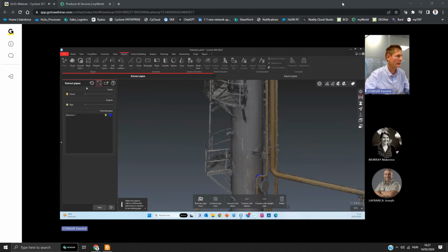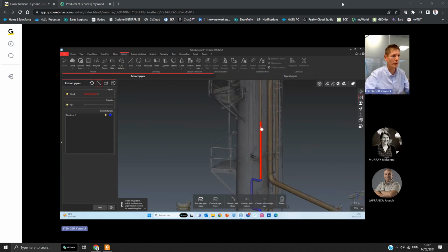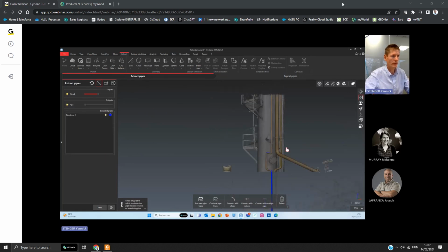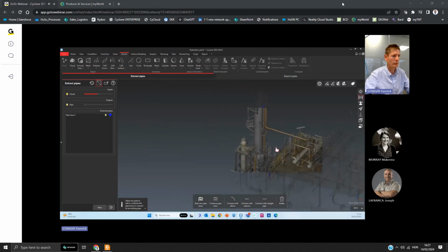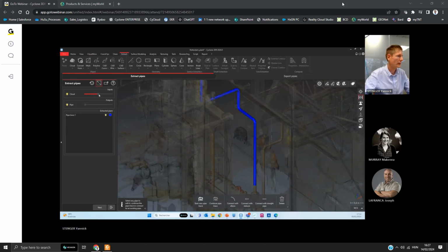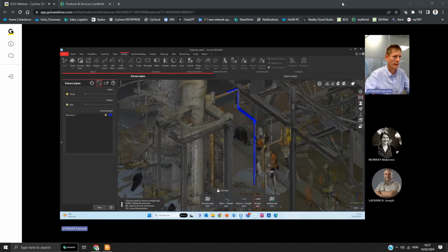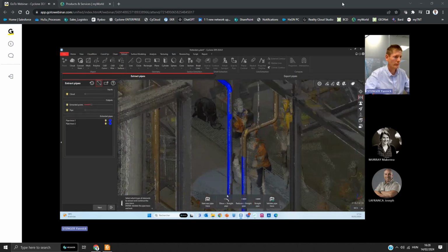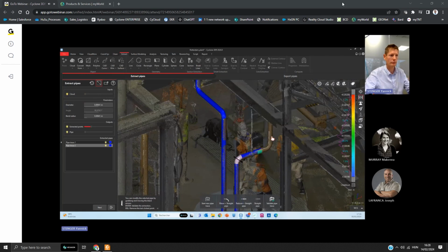And okay, if I'm satisfied. Also, nice tips that we introduced to hide or to change the transparency of the point cloud. Even when I'm not editing or creating a trace, I have the possibility to do some adjustments, and I can create a new trace. So I will do this one. I click enter, always first step, creation of a straight pipe, and then I click enter to be in the next mode, so elbow plus straight pipe.